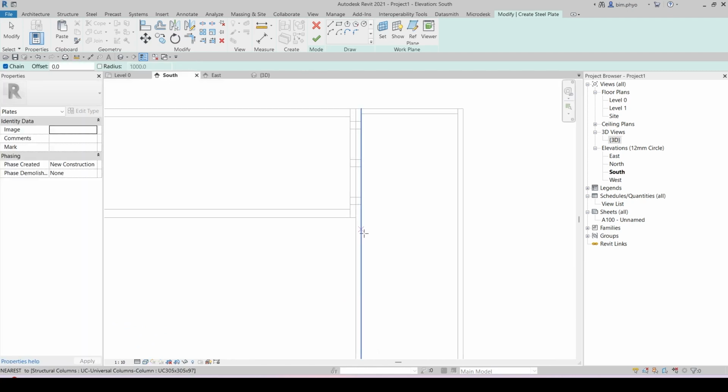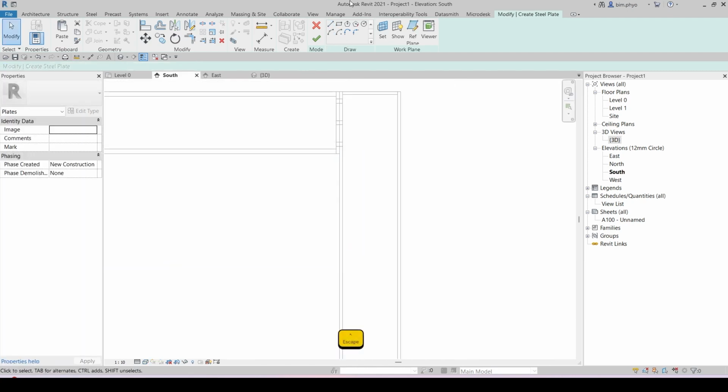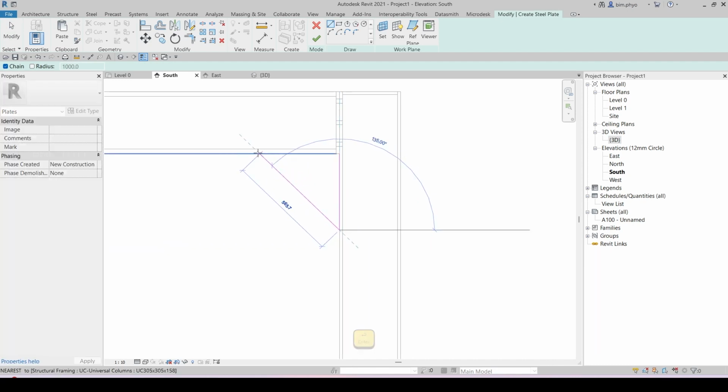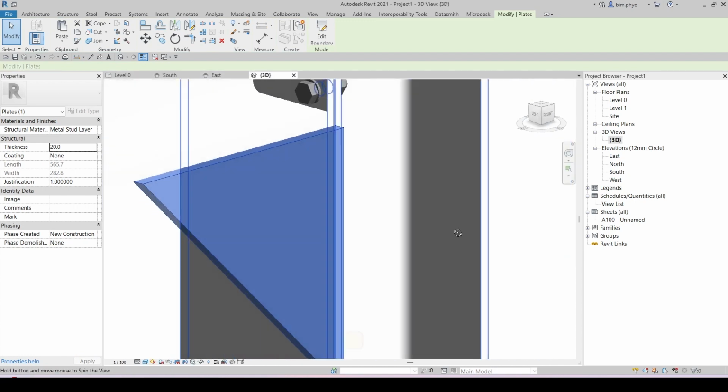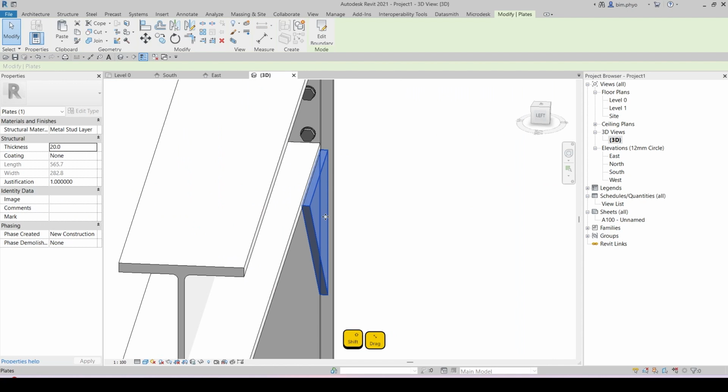So we're going to the soft view. Exactly I want 400 millimeter by 400 millimeter, then I'm going to 45 degree and just use this. Then what is the thickness size? So 20, I will choose a 20 plate. Then you look into the positioning where exactly it is. It doesn't really look good, so I need to put it back inside.